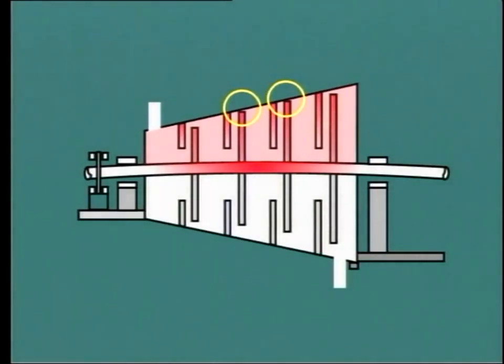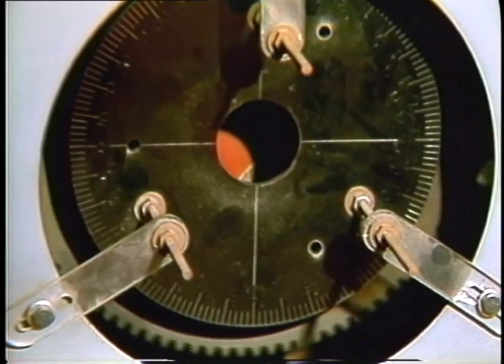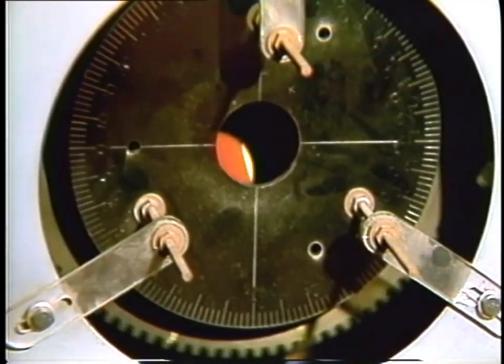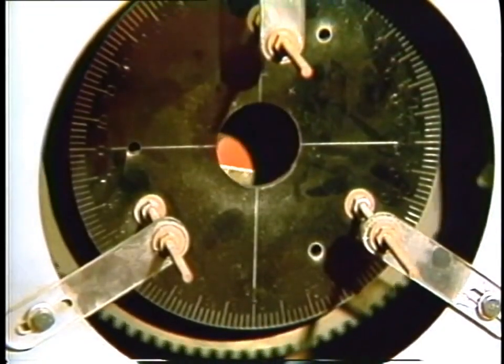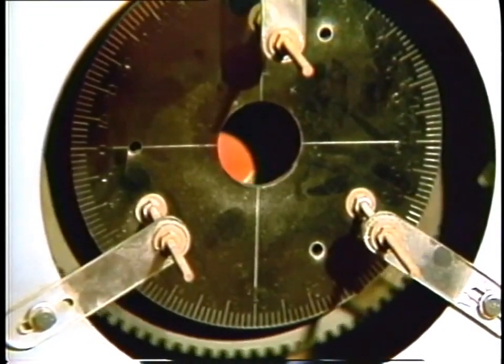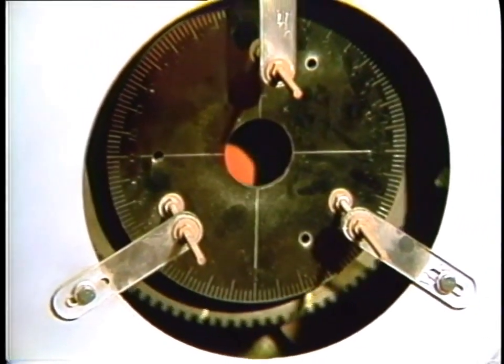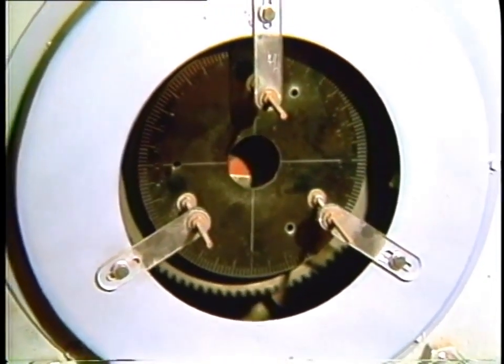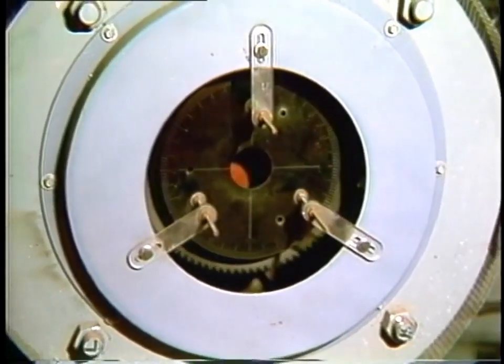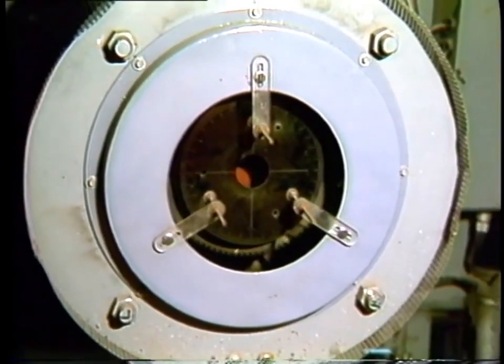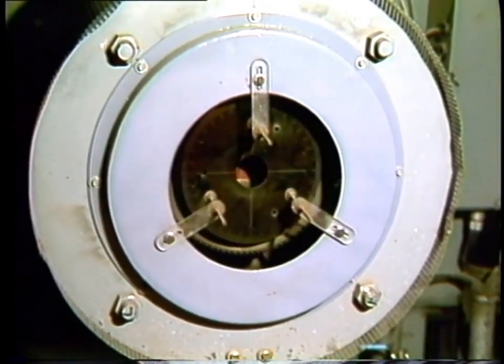To prevent this problem, it is essential that the rotor be placed on turning gear immediately after the unit is taken out of service. This ensures that the heat is evenly spread around the rotor and there is consequently no chance of distortion. It should remain on turning gear for several days at least if a long outage is contemplated.